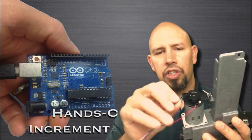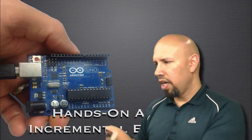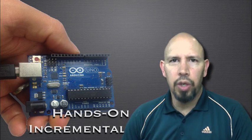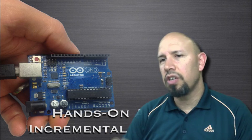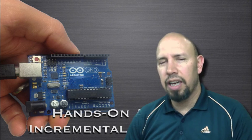These 3 wires show that this is not a quadrature encoder. This is only used for unidirectional, one directional encoding, what we talked about last time. And so that is primarily used for counting the number of times you've gone in a certain direction, or for estimating the speed. And we'll see how to do that in a little bit.